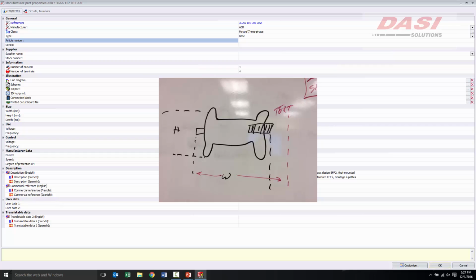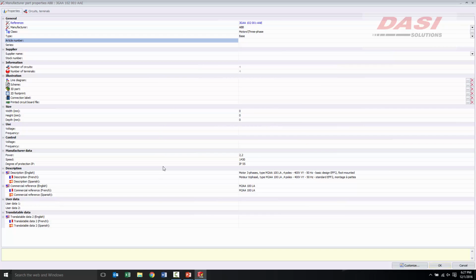Any type of attributes or anything is typically on the inside, on the footprint. I learned right away that I didn't want anything outside, because you're drawing things, so it really didn't matter. So I always tried to keep that text inside the footprint. Yes, of course, learning that took like 2 years. I was having a lot of problems with that. Yep, that's where that comes from.